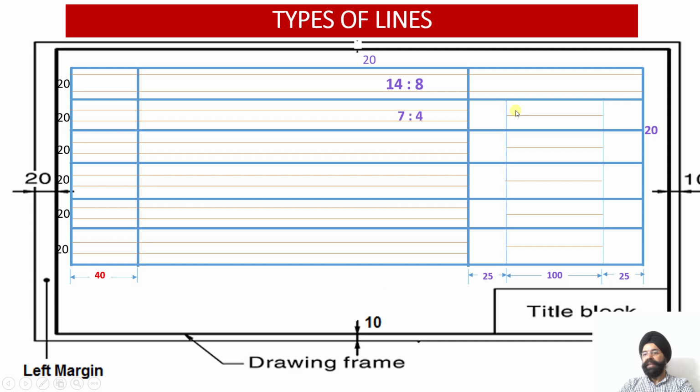Now here I have to draw all my conventions in the middle of this 20 mm. So this distance left is now 10 mm. So I cannot write 7:4 because space is less. I will write the thick line, thin line or medium line in the ratio 5:4. So this is 7:4 doubled because this is a title. This is 7:4 Gothic and this is once again 5:4 Gothic because lesser space is available.